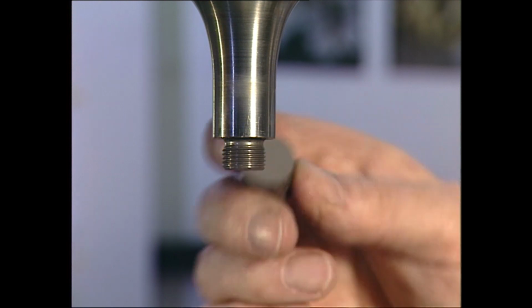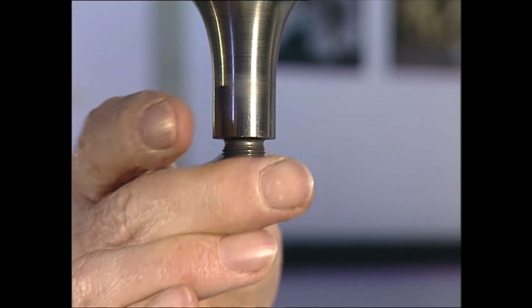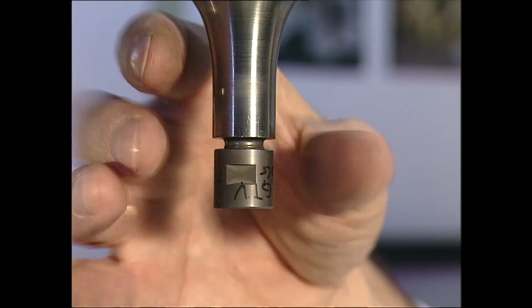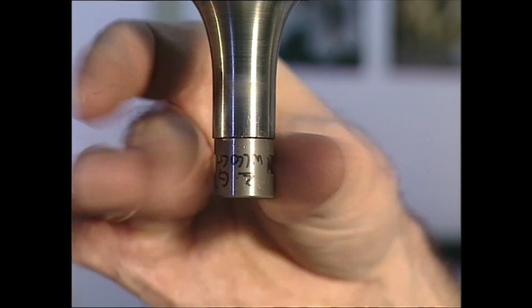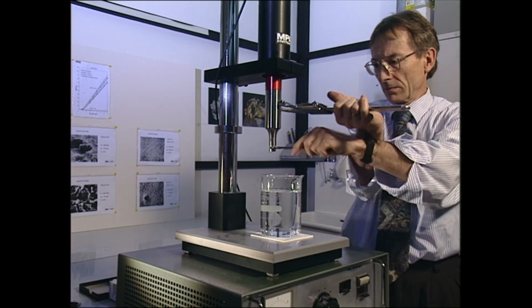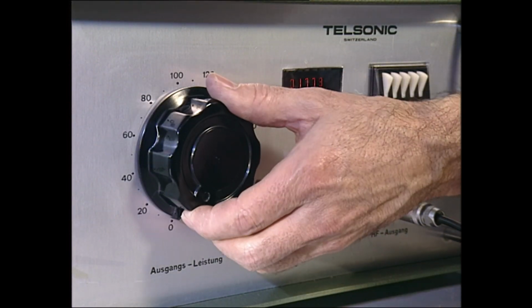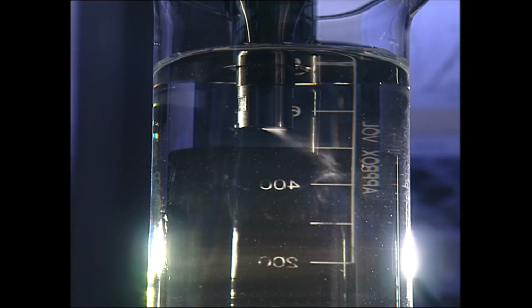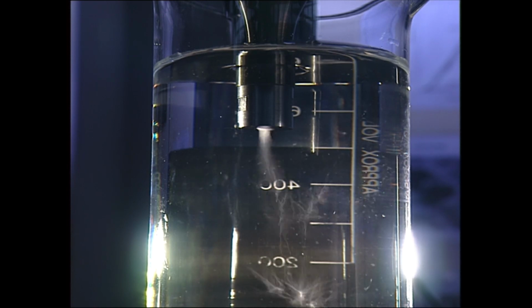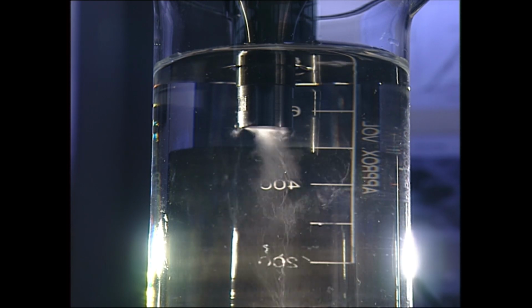Thermal sprayed hard coatings can be tested for cavitation resistance with an ultrasonic test device such as this. The vibration of the test body is accompanied by a periodic pressure drop below the vapor pressure of water.